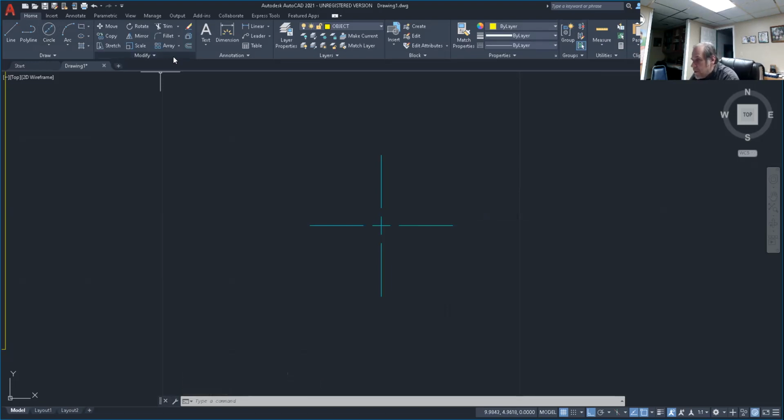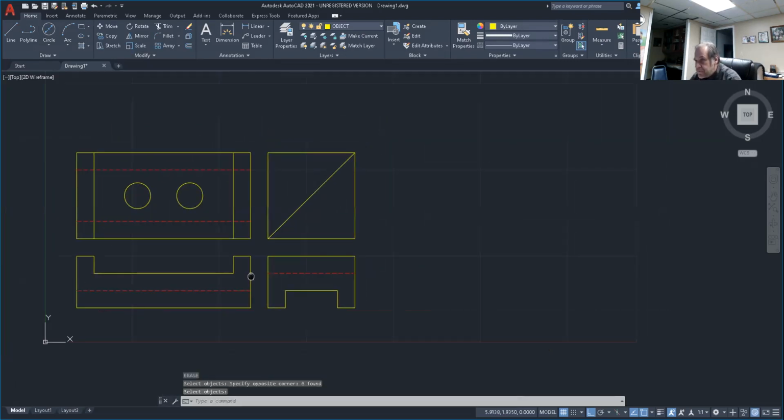Now, let's see how much faith you have in yourself. We took the time to draw this center line. Let's erase it all now. So E, enter. Okay, so it's gone. So what we're going to do now is bring it back. We're going to see if the W block really worked. So to do that, you're going to use what's called the insert command. So let's type in insert. You'll also see the insert is right here. So I-N-S-E-R-T, enter.